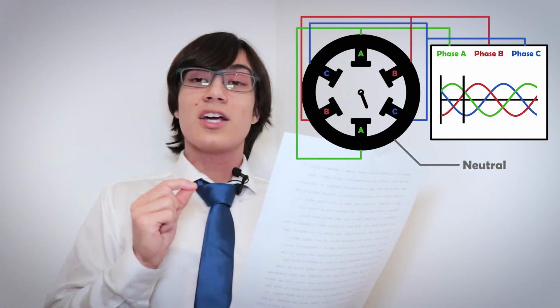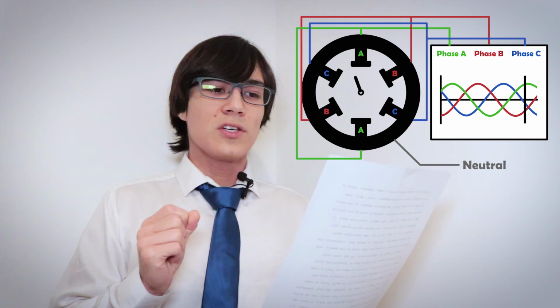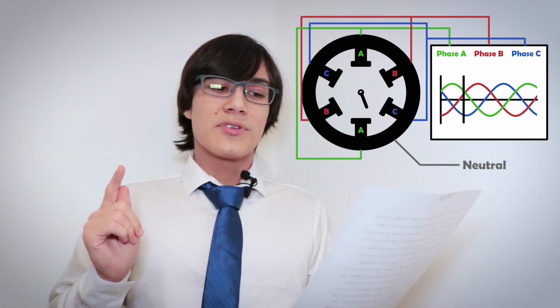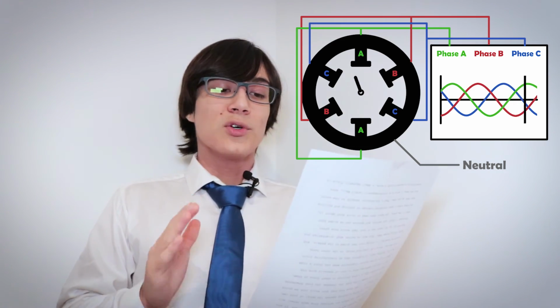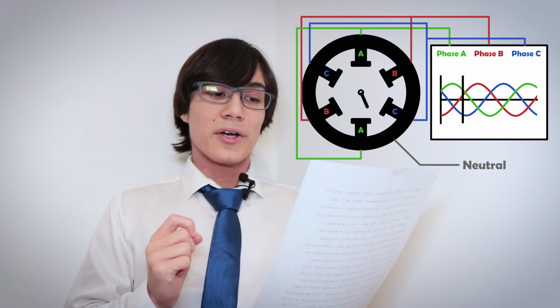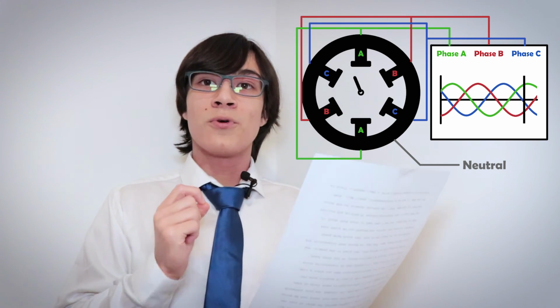Now, if you place a closed-circuit conductor in the middle of this field, like a loop of wire, perhaps, the changing magnetic field will create a magnetic flux in the wire, induce an electromotive force, or EMF, which will create current running through the wire. This will create a Lorentz force on the closed-circuit conductor, which will physically rotate it, and boom, you got a motor. The only caveat is that the magnetic field needs to be moving faster than the motor itself, or else you don't have any change in magnetic field, it's just a constant magnetic field. But other than that, it's perfect.